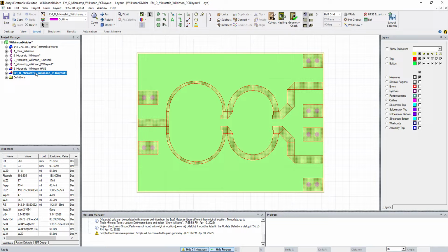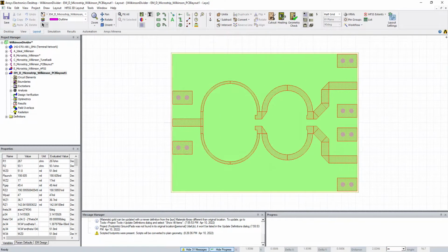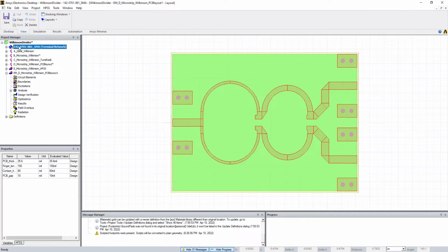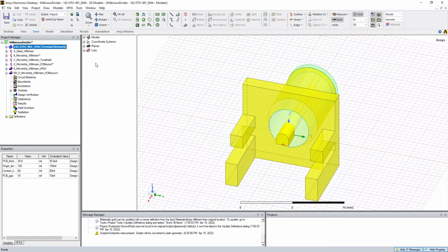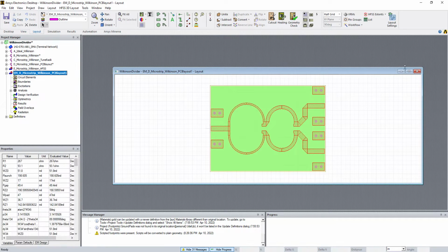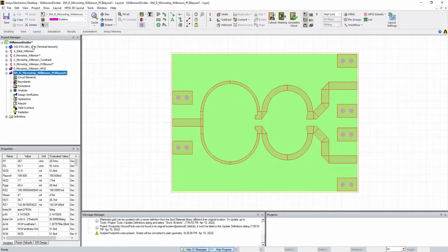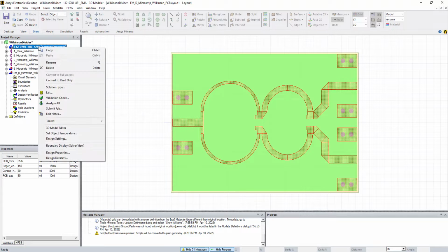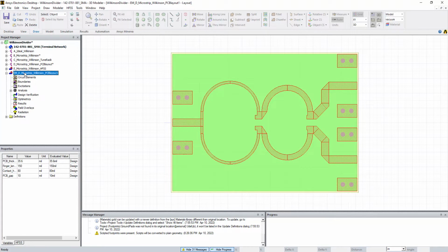And of course it creates this guy, and we've done this before, but I'll just do it real quick. So the only thing you're going to do at this point in time, you're going to add your connectors. So you remember how we brought in this connector to it. Remember, this is our SMA connector guy. Let me just close all these windows. So what you're going to do is, we're in the HFSS 3D layout. We press this, we hit copy, go down here and say paste.